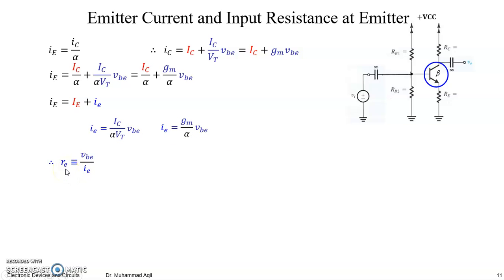Again, looking into the emitter, if you are having a voltage and you are having a current out of or into the terminal, for NPN it would be out of the emitter, for PNP it would be into the emitter, and a voltage across that terminal about some other terminal, you have a resistor actually. That component can be modeled as a resistor.